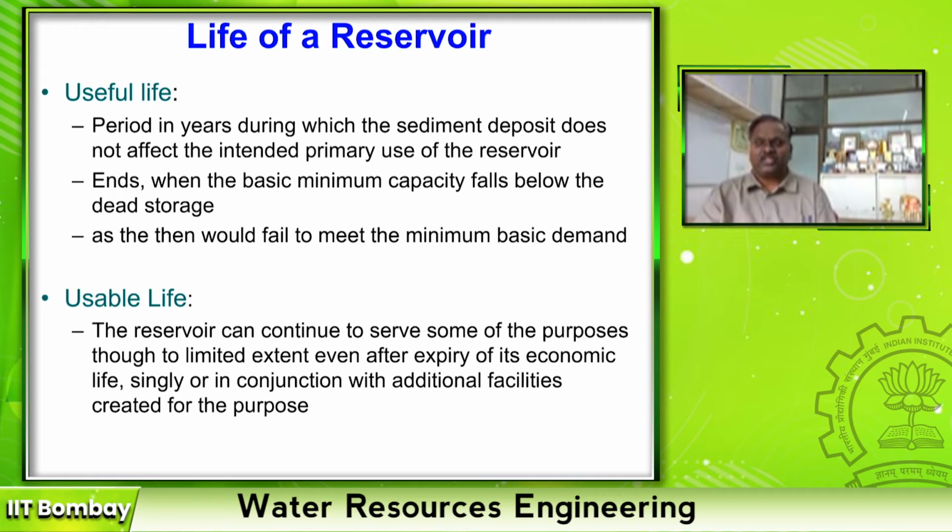That means the dead storage is sufficiently designed so the sediments are not seen in the outflow of the dam, whether it is for irrigation, power production or drinking water purpose. The end of this useful life is when the basic minimum capacity falls below the dead storage, and then it will fail to meet the minimum basic demand.